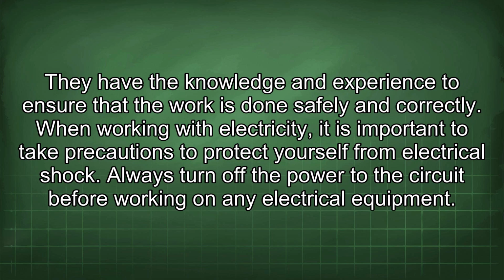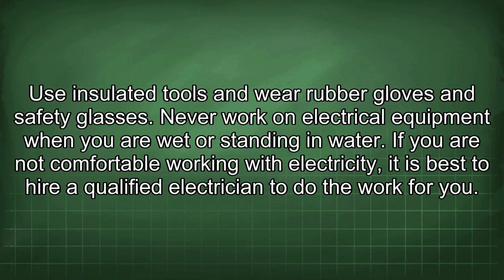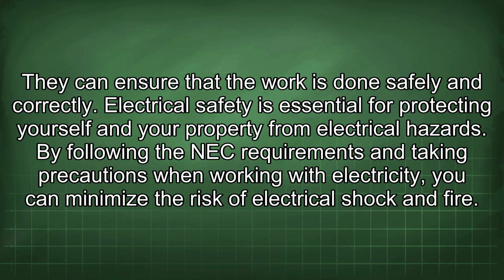When working with electricity, it is important to take precautions to protect yourself from electrical shock. Always turn off the power to the circuit before working on any electrical equipment. Use insulated tools and wear rubber gloves and safety glasses. Never work on electrical equipment when you are wet or standing in water. If you are not comfortable working with electricity, it is best to hire a qualified electrician to do the work for you. They can ensure that the work is done safely and correctly.